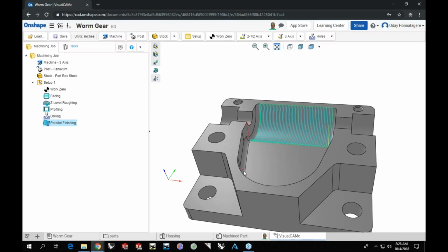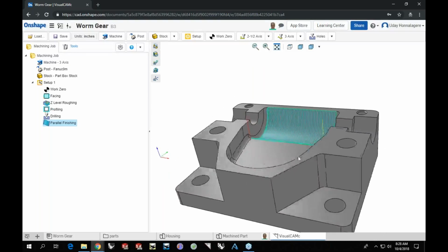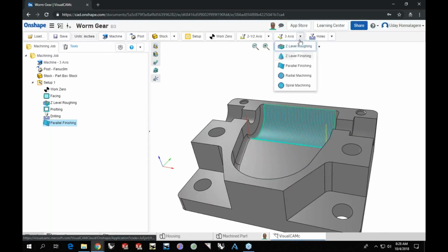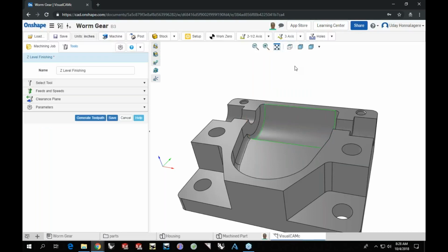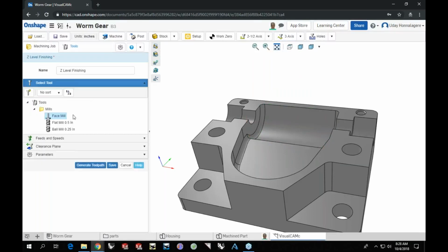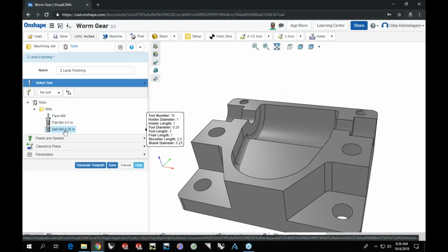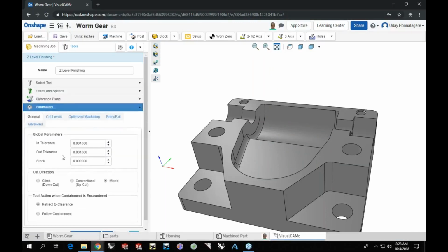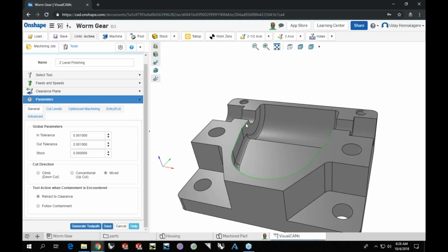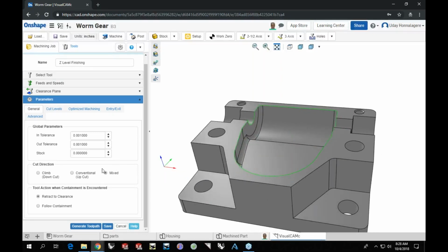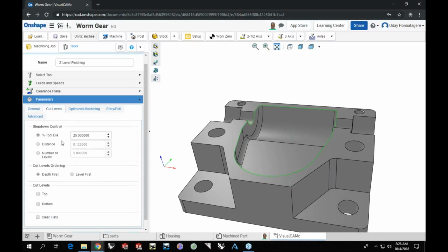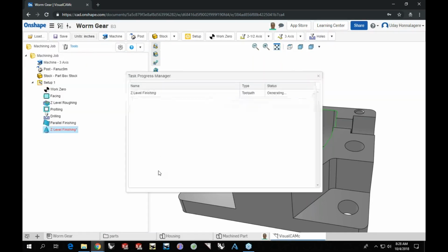Now to finish these fillets along the sidewalls, I'm going to use another 3-axis finishing operation in here, and this would be a Z-level finishing operation. So you could program a combination of 2 and 3-axis operations. I'm selecting the same ball end mill we used for the parallel finishing. And for this, I'm going to pick this region in here to contain the toolpaths. The regions have been selected. I could specify the cutting conditions in here. I'll use a step over of 15% and generate it.